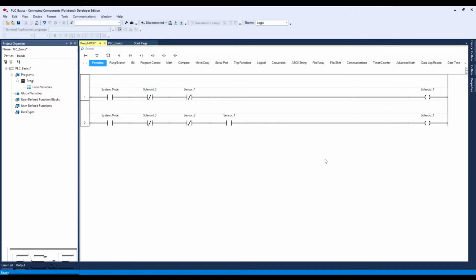Now this is a personal preference, but I always like to have the last condition of the rung be the condition that will trigger the output. This is especially true when you are building a real sequencer. Last, we need to change the output for solenoid 2, as well as add a parallel branch for our motor output. We do this by selecting our toolbox and click, hold, and drag the branch out to the spot in front of our solenoid 2 output.